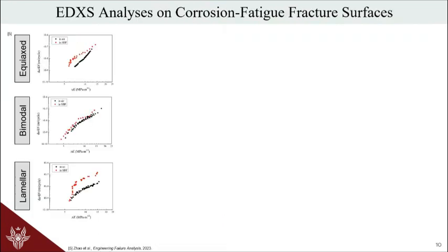We tried to understand if our hypothesis of different energy dissipation mechanisms between the two types of specimens could find agreement in the literature, and we actually found agreement in a work by Zhao et al., published in 2023, particularly considering that our microstructure is a lamellar microstructure, in which, as you can see from the fatigue crack growth rate tests, we do have severe differences between a body fluid solution and an air-tested one, particularly in the Paris regime.